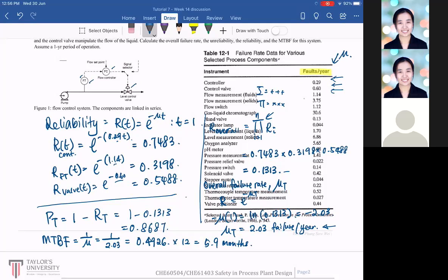Also, if you're doing hazard analysis in your final assessment, I will focus more on the suggestions that will prevent it from happening, what we call inherent safety. Not just preventive, but building in a safety system that's inherent, like reducing the chemical flow, reducing the temperature of the reactor, for example. Those are the things that I will be looking at.